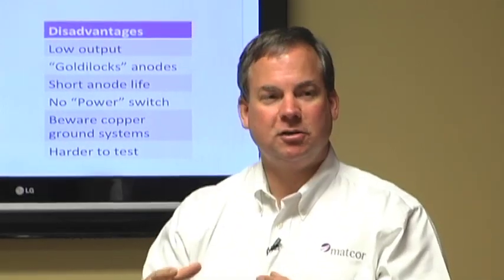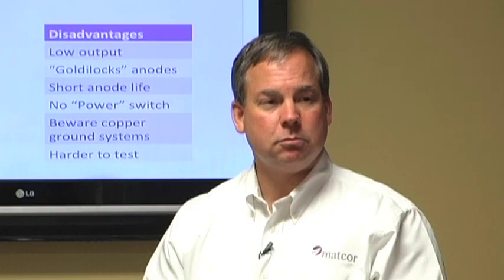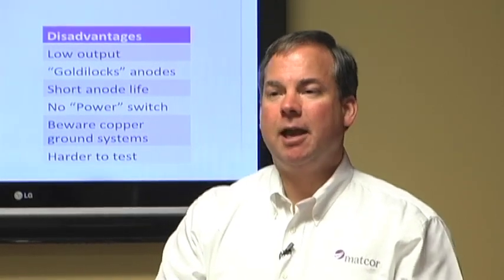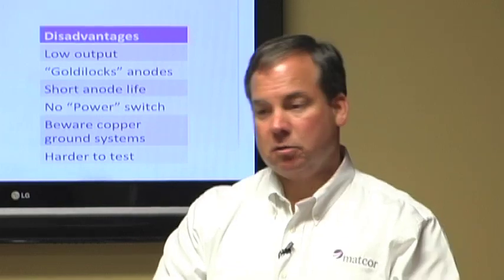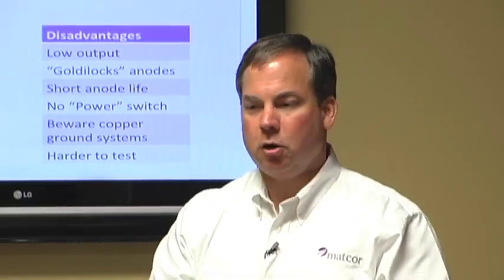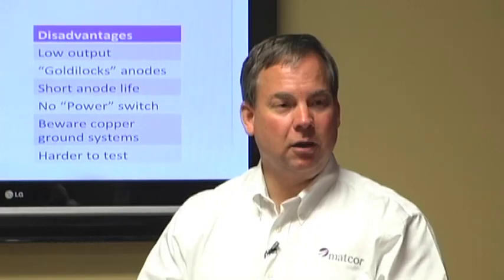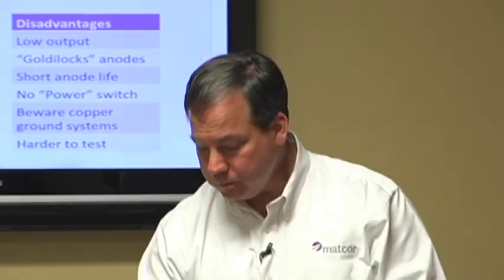So those anodes, it's just like a light bulb's rated for so many kilowatt hours. An anode is rated for so many amp hours. So if you know it's doing 200 milliamps, excuse me, when you measure it, you can calculate how long it's going to last based on how much weight it has.